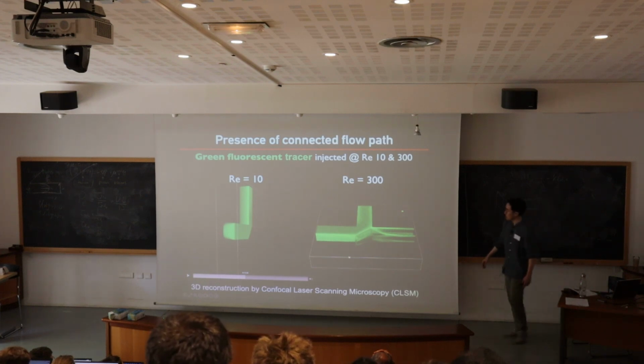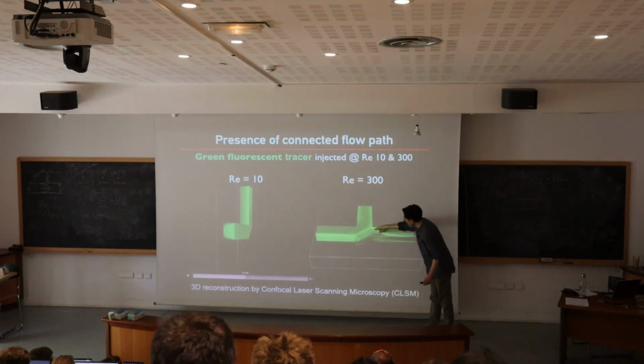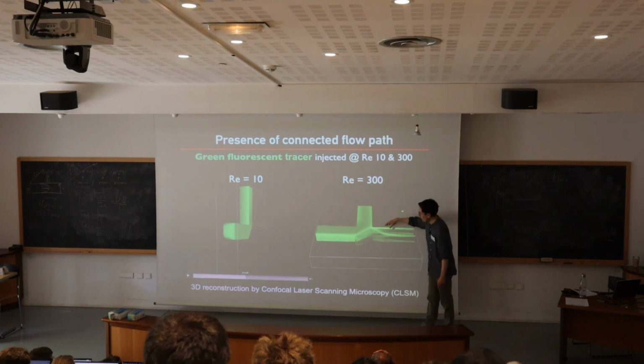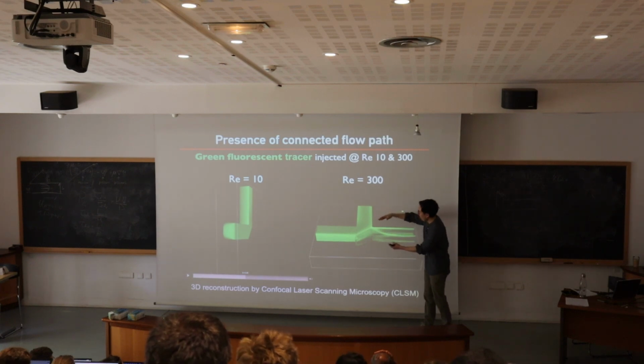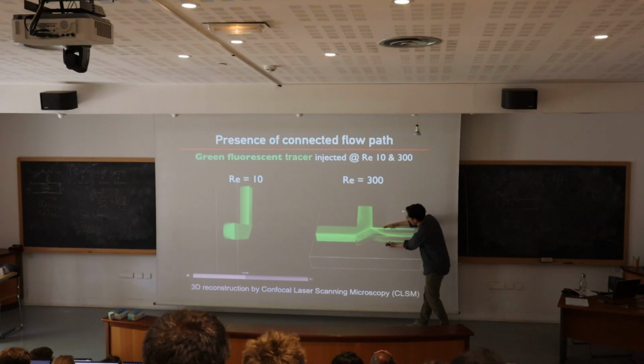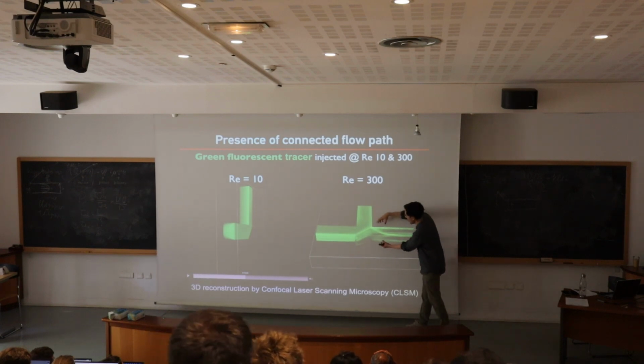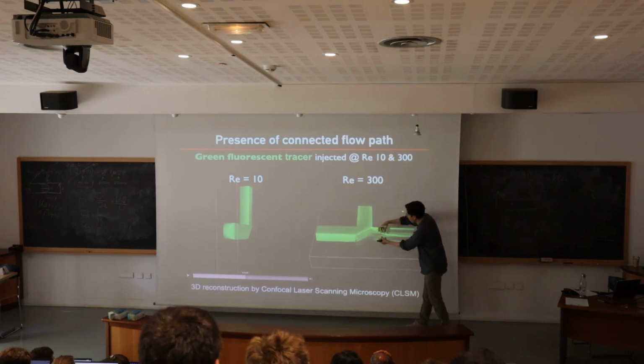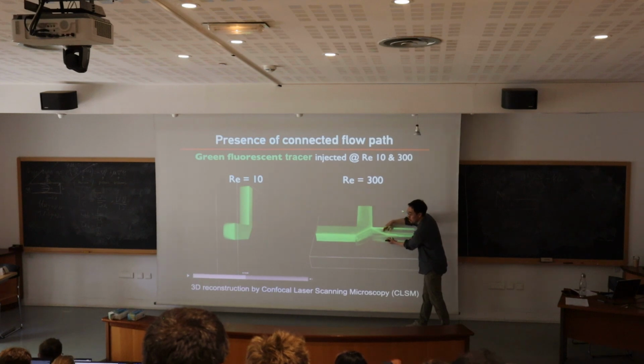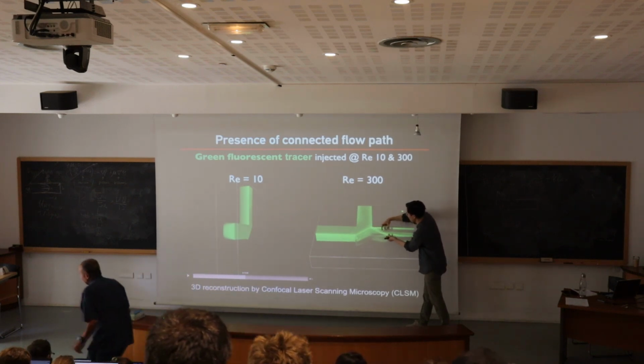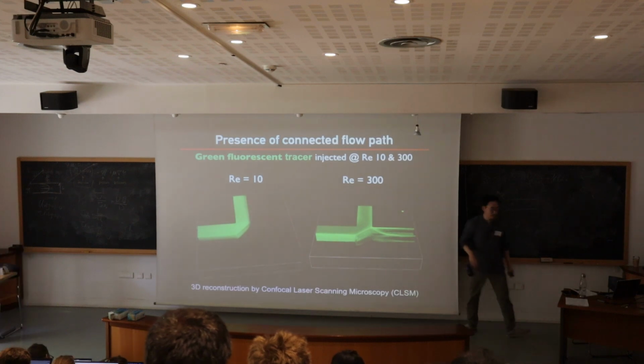But in 3D, if you see the side view, you see a three-dimensional flow pattern, and that is actually what's happening. A lot of concentration is moving along the top, which I will show you, but it all concentrates due to the recirculating flow into one spot. So the concentration comes in as a sheet, but then it focuses into a very local hotspot.